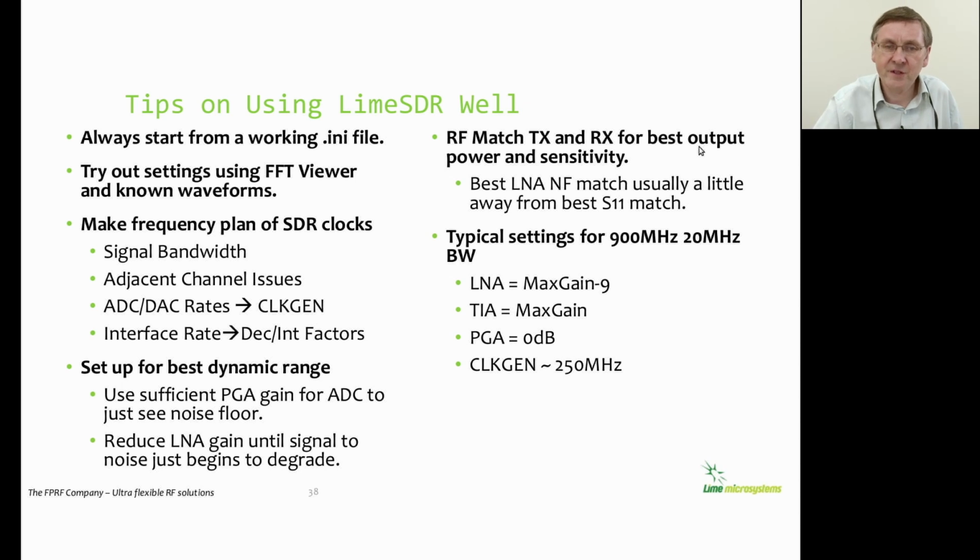So, tips on using the LimeSDR well. I think one of the most important ones is to start from a well-defined working set of initialization files. We give example files for different applications, and then using the FFT viewer and our loopback configuration, you can optimize the settings of the radio for your particular application. Make sure there's some sort of frequency plan for clock frequencies. For example, you don't want the clock frequencies interfering with your signal.